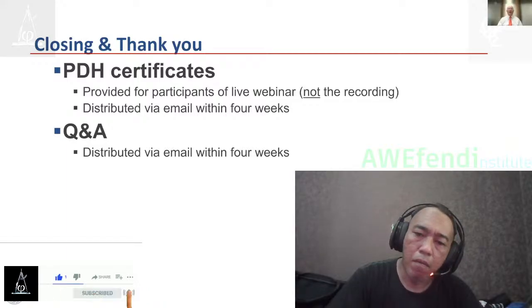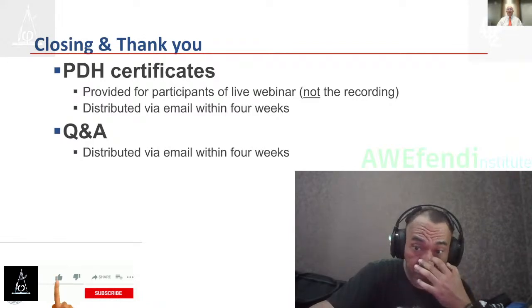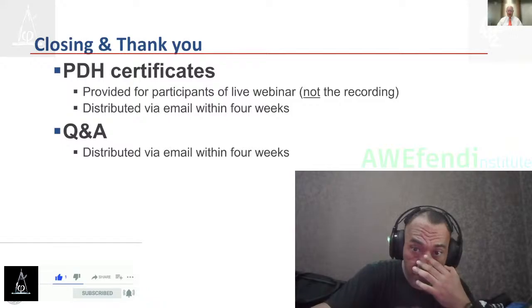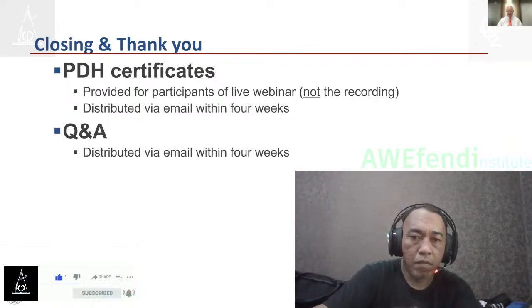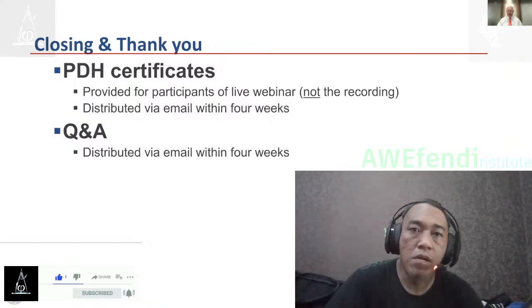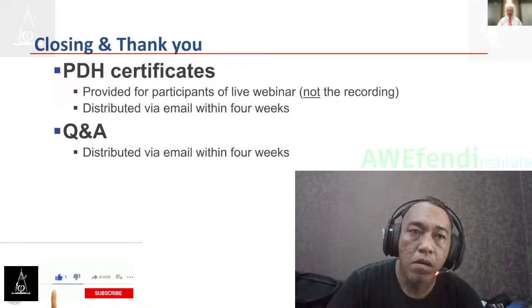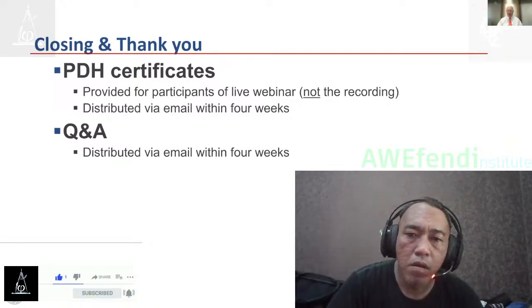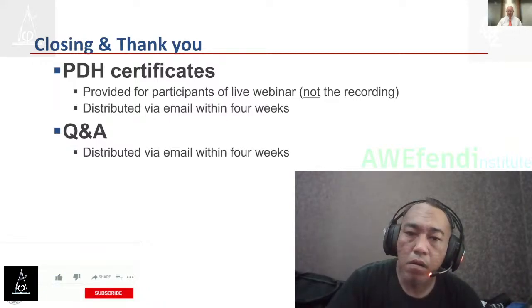Yeah, I think all of our inelastic response can be affected. I live in the Pacific Northwest. I live in Seattle, and we have subduction zone sources off the coast. And the reality is, for very tall structures, we could expect that 3 minutes of shaking at a large displacement, the number of cycles could cause poor performance as compared to a closer earthquake that had only 1 or 2 cycles of inelastic response. That's probably generally true, regardless of irregularities.